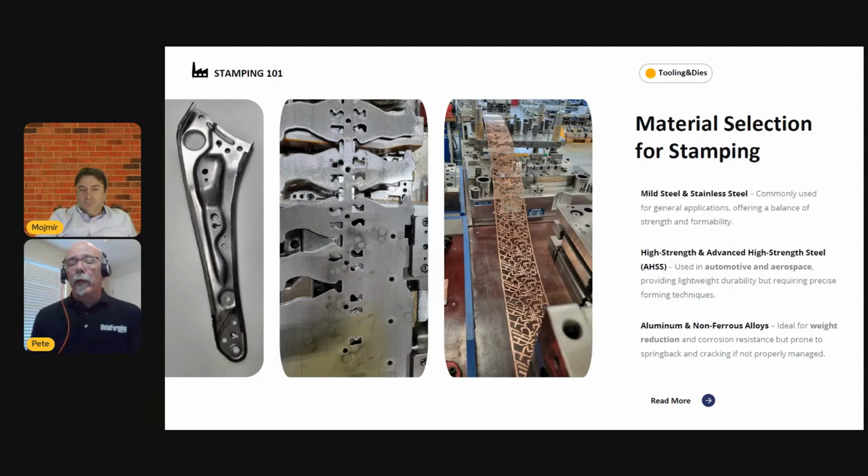Dual-phase materials are primarily ferrite, but they'll have these small islands of martensite distributed all through the material, uniformly distributed. This martensite gives the material its high strength. The ferrite in it is what gives it its formability. That's why we can take today and have a pretty high degree of formability out of very high strength materials.